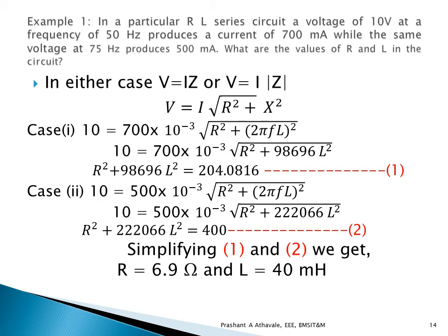So XL value depends on the frequency. For 50 hertz, whatever is the inductance, the inductive reactance will increase if it is 75 hertz. So that is very much obvious. You can write down some hypothetical example and then calculate for value of inductance for 50 hertz as well as for 75 hertz. So as the value of inductance increases, obviously the magnitude of the impedance increases.